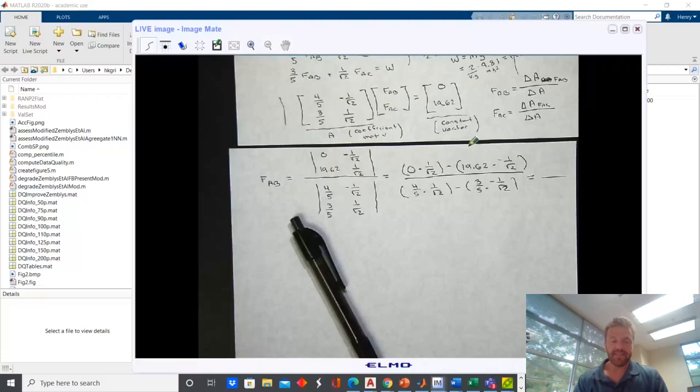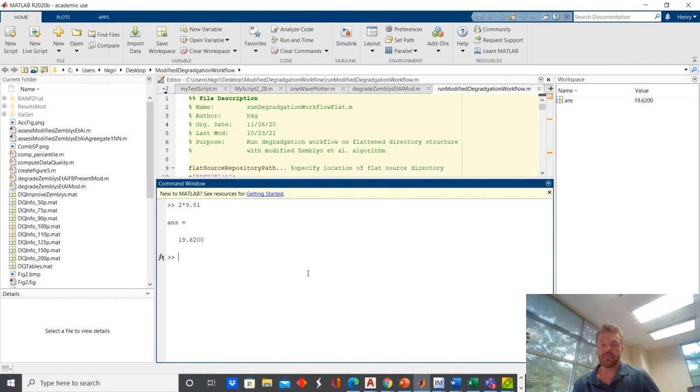So you can compute what that is in a calculator and solve for it, but I assume that many of you are just going to put this into your calculator anyways. So let me show you how to enter a matrix into MATLAB if you wanted. The way that you can enter a matrix into MATLAB is to enter row elements separated by commas, and I should say within a row, separate each element by a comma, and to go to a new row, enter a semicolon. So this is how you would enter the first row of the coefficient matrix.